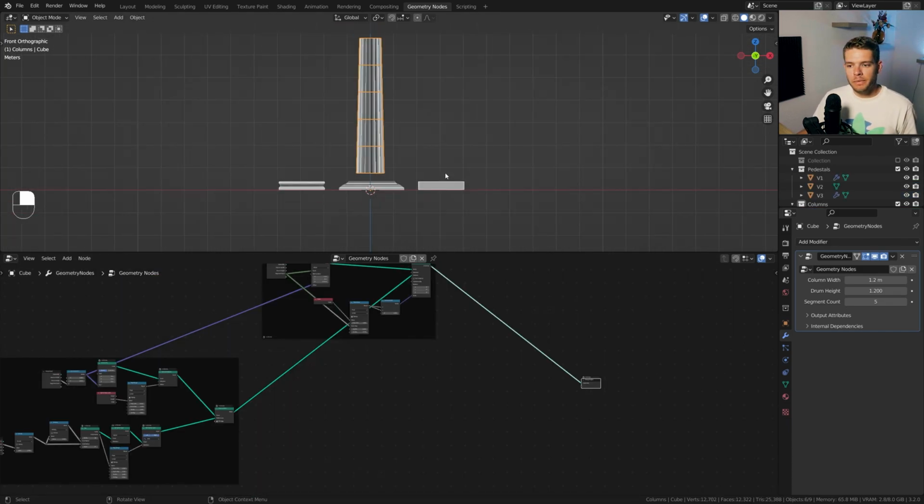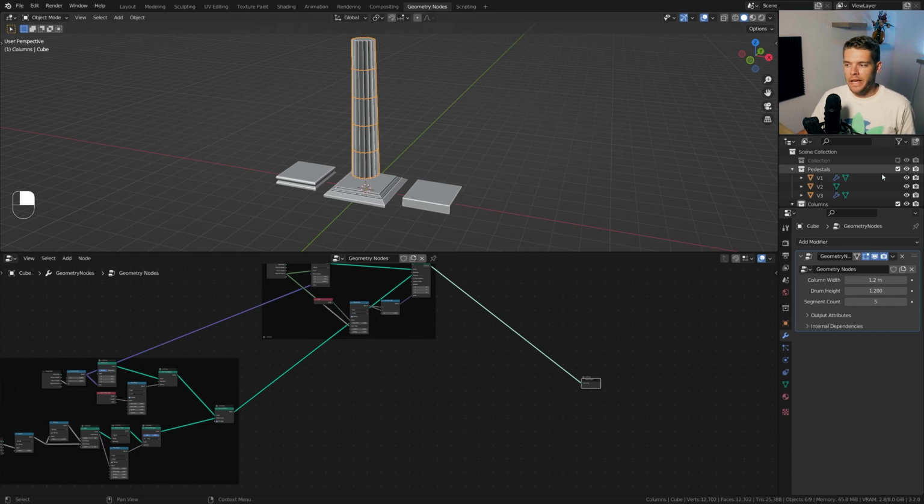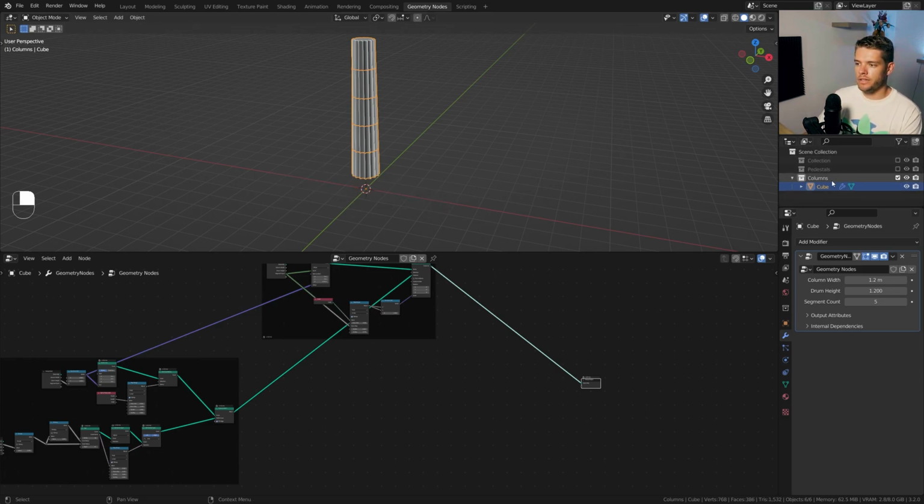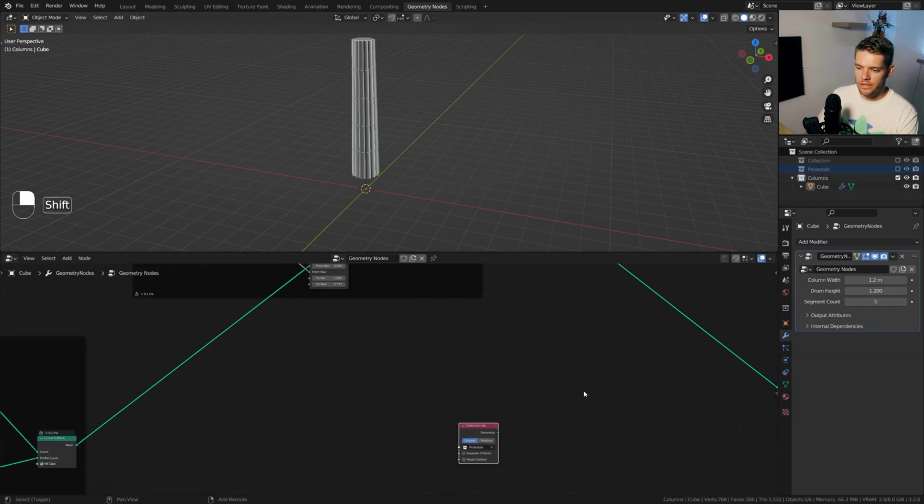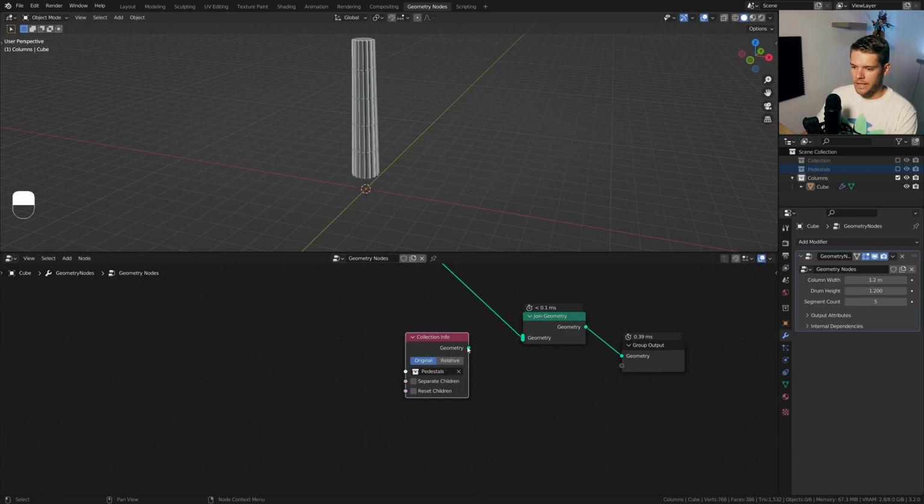As I showed you in the start of this video, we have this collection of pedestals already in the base file. So we have 3 over here, and we can actually use this within geometry nodes. So I'm going to disable the collection there again, but I'm going to also click and drag it inside of our geometry nodes system. Now, if I add a join geometry node and take this collection info and plug it in there, you'll see that they are now within our geometry node system.